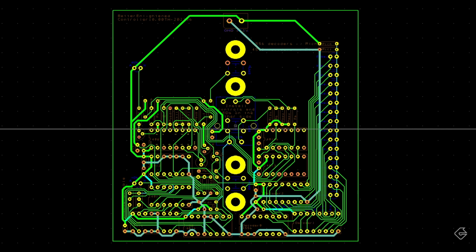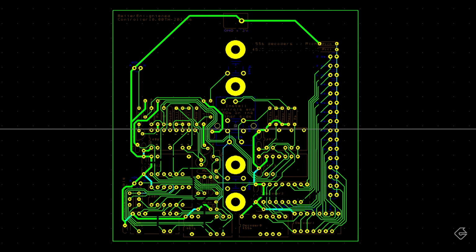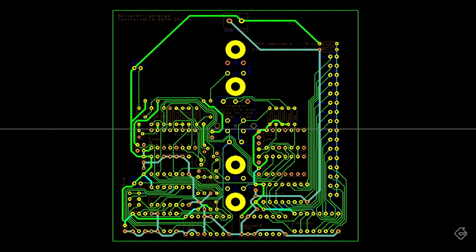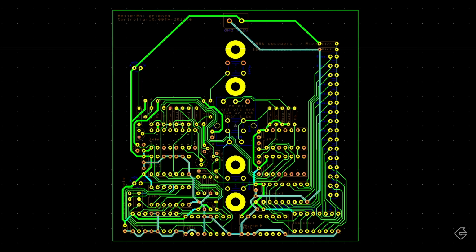So the bottom side of this board, and you can tell by the light blue color for most of those nets, are connected. But all of the components that we added today, we deliberately did not connect the ground components, but you can see how they're everywhere. So if I wanted to do what I did last time and try to connect every single one of those pads together, I could do that. But I've discovered an easier way, and it's this idea of a ground plane.